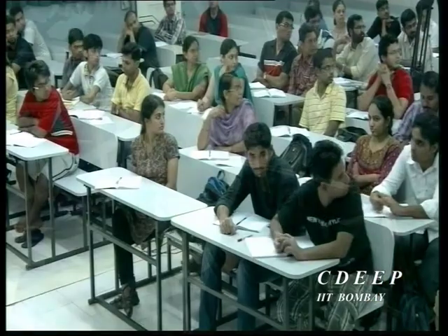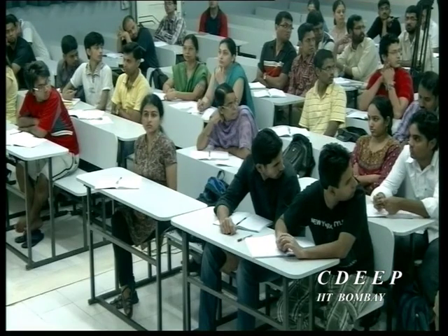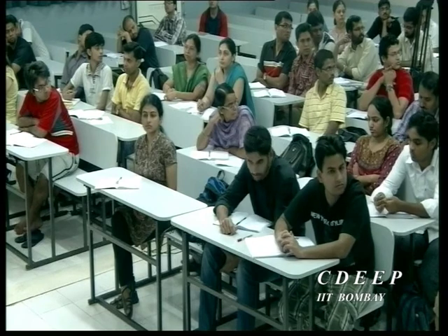Yes, please. Yes. So, very good. So, the question is, if you did indeed write r to the power of n as r raised to the power of n u[n] plus r raised to the power of n u[-n-1], how would you deal with it? That is exactly the problem. R raised to the power of n has no Z transform, or has no Z transform in the sense of conventional functions. You will need to introduce impulses in the Z domain to take the Z transform of r raised to the power of n.